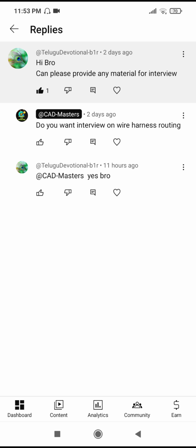Okay, and then at the end, once 3D is completed and after the 3D flattening drawing is completed, form board drawings are also created. For that, different software is available. The drawings are prepared at a 1:1 ratio. They are called form boards, and everything is mentioned properly in them. They are made by using 2D routing.